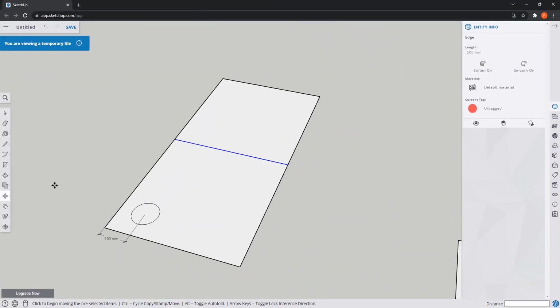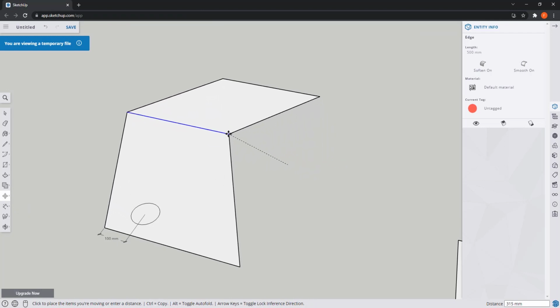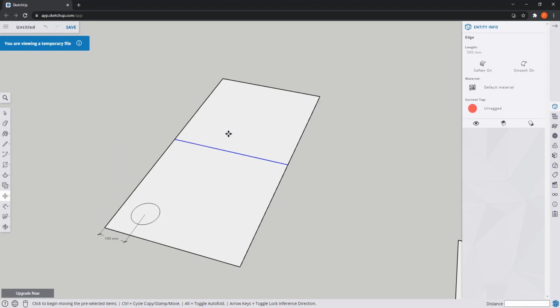However, there could be a problem if I want to move the line to the sides, as once again I'm deforming the face. This happens because the line is intersecting the edges and the Move tool does not disconnect them automatically. On the other hand, it won't be a problem for objects drawn on faces when they don't intersect anywhere.